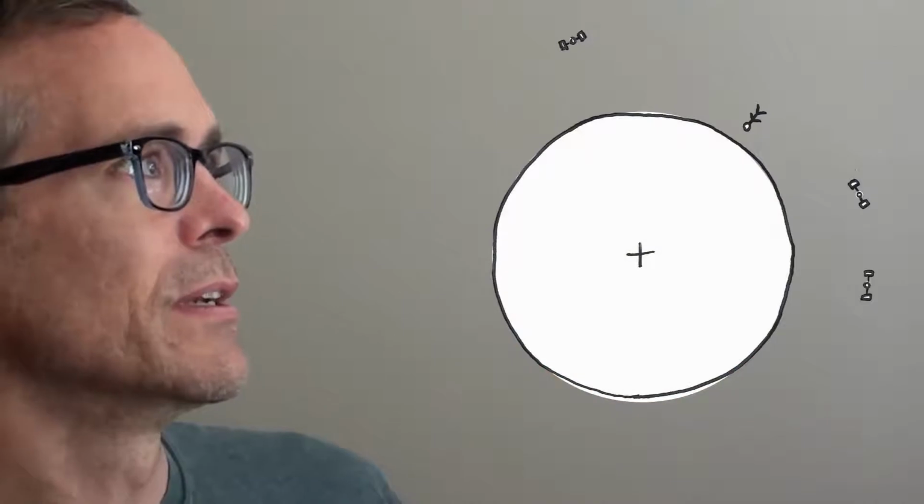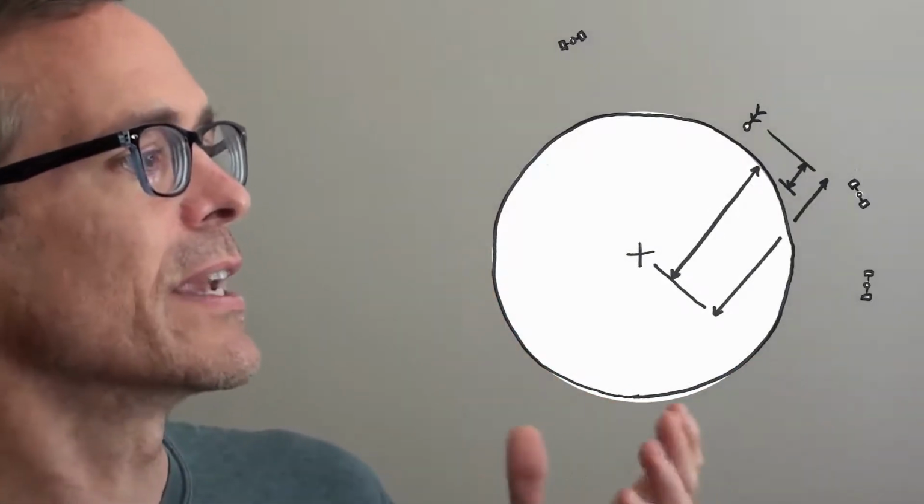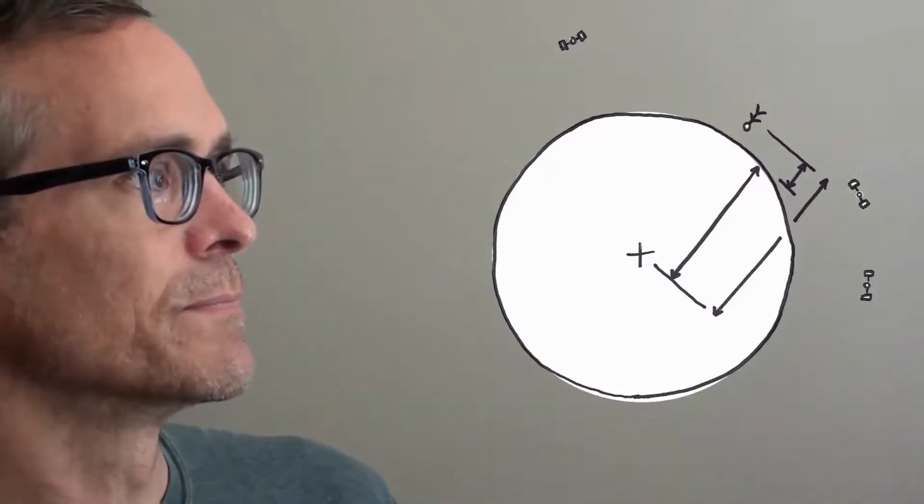Before we get started, I wanted to clarify something I said in the previous video. I'd said that GPS measures your actual height above ground, but that isn't quite true. GPS measures your 3D position relative to the center of the Earth, but the GPS system doesn't actually know where the surface of the Earth is, so in order to convert this 3D position into height above the ground, we need to define the ground elevation. And once we do this, a little math gives us the height above that ground reference.